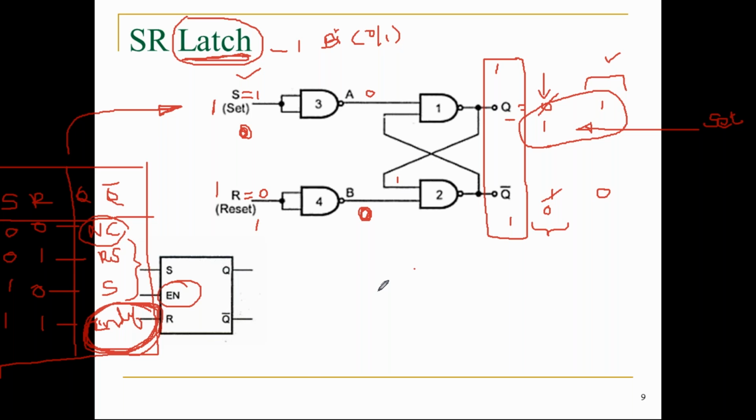What is meant by a sequential circuit, and the comparison between combinational and sequential circuits. The combinational circuit depends only on the present state. A sequential circuit, in addition to the present state, also considers the previous state. Then the classification of logic circuits: synchronous sequential circuits, asynchronous sequential circuits, and the overall classification of digital logic circuits, we have also discussed so far.